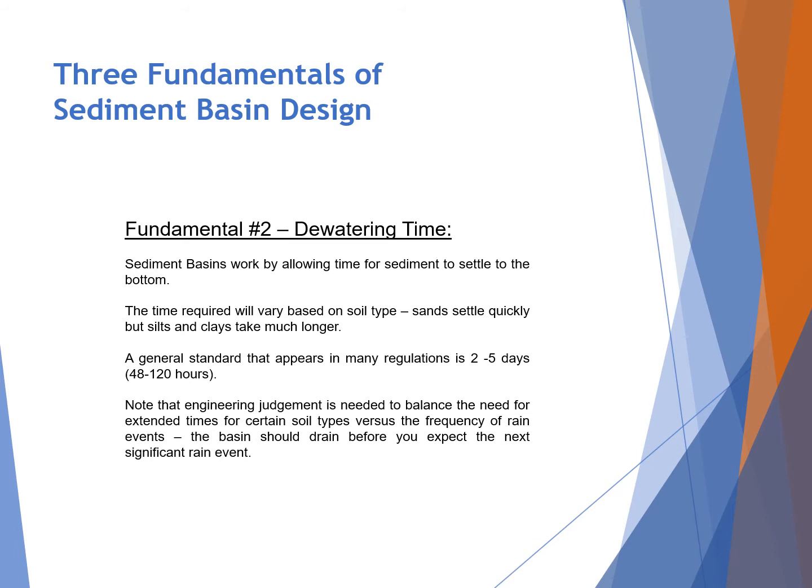Fundamental number 2 is dewatering time. The general rule is that sediment basins work by allowing time for sediment to settle to the bottom. The time required will vary based on soil type. Sands will settle quickly, but silts and clays take much longer. A general standard that appears in many state regulations is 2 to 5 days, or 48 to 120 hours. Other states require 2 to 7 days. Some states have a 4 to 7 day period, and other states have no standard and leave it up to the engineer.